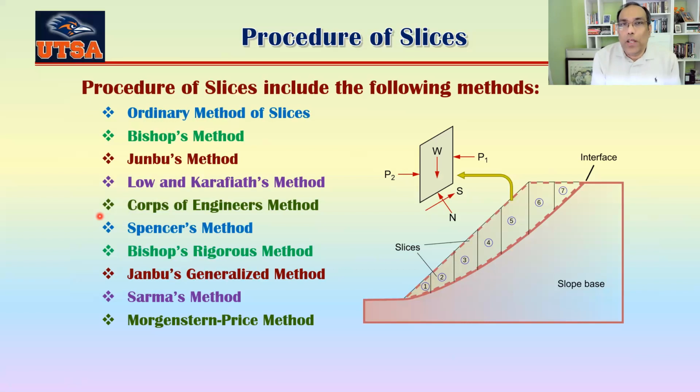So you can show them that actually your software is working well, okay? Otherwise, sometimes it might be a black box how this is working, and the reviewer might have a problem understanding what you did there and whether this is following the hand calculation, okay? That's why now it is kind of a requirement that at least one failure surface simulated in your software has to be hand calculated, and you show that your results are pretty close to each other, okay?